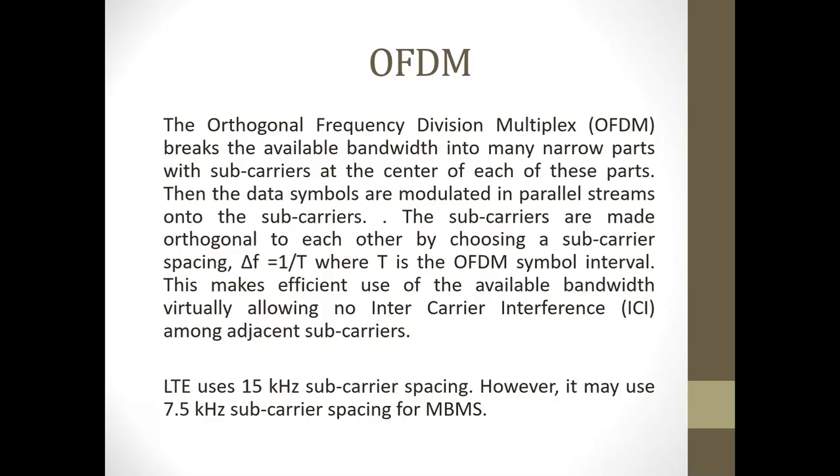Although there is a relationship, it's possible to try both domains. But in the frequency domain, you should keep the subcarrier spacing fixed for your technology to ease your implementation. When you use a fixed subcarrier spacing, your RF circuitry will be simple. So that is held fixed at 15 kilohertz for LTE. So LTE uses 15 kilohertz. There are some variations